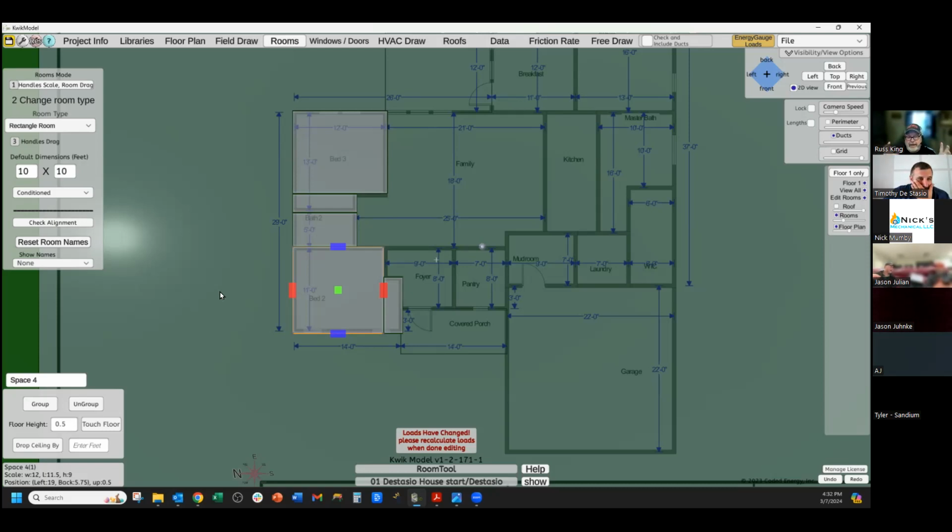But what really helps is after I do a load calculation, I'll show you. It really helps a lot as you're doing these. Do a house, and then take a few extra minutes and sit down, copy and paste the loads, save them off to the side, and then make one change to the house. Then run the load calcs and compare that to your previous load calcs. And then do that for each different kind of measure. Do it for the windows, do it for the infiltration, do it for the wall R value. What happens is you'll start learning what's important and what's not important, and you'll start realizing, I don't need to be super precise on this stuff. Comparing before and after loads really helps a lot.